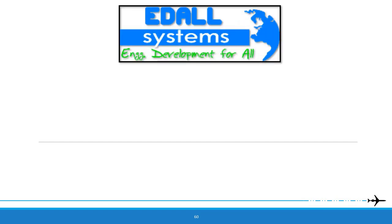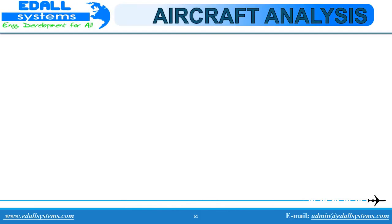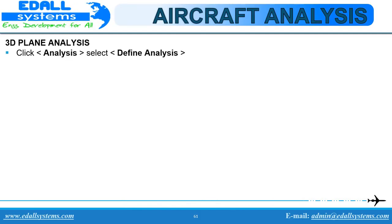In our previous session, we had seen about the fuselage design. In this session, let us start with the aircraft analysis. We have the 3D plane analysis. For analysis, click on the analysis in the toolbar and select the define analysis option.